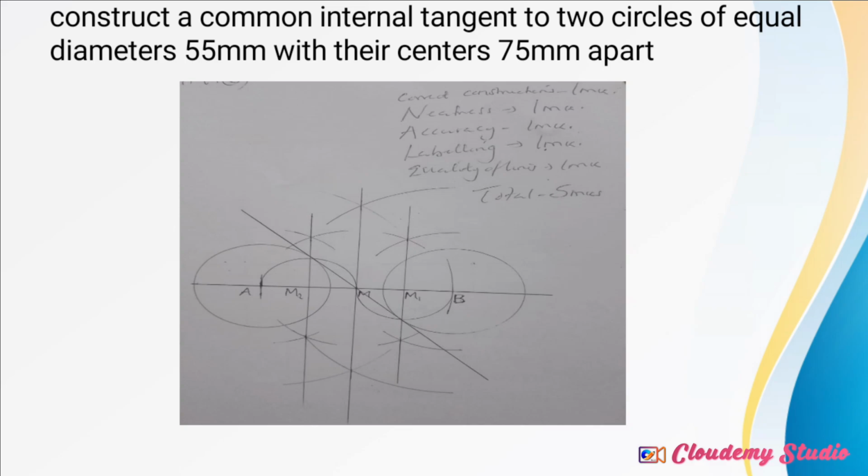Then to get another semicircle, I will start at point M1, which is our second midpoint, the second minor midpoint, because it's in between M and B. I draw an arc that goes downwards. That arc will run from point M to point B. So you'll find that that arc will cut the circle at some point. So that's where I'll join those 2 points to form our internal tangent. So that's the same case on how you can construct that.